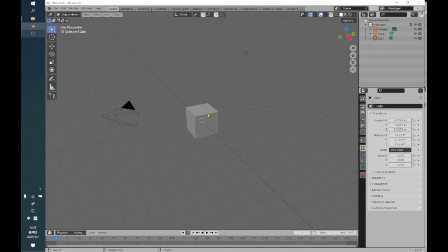But in general, when in doubt, keep the objects apart, and always keep a copy of the version of the model with the different objects. Then when you come to export, you save it under a new name, and unify the objects into one before you export.